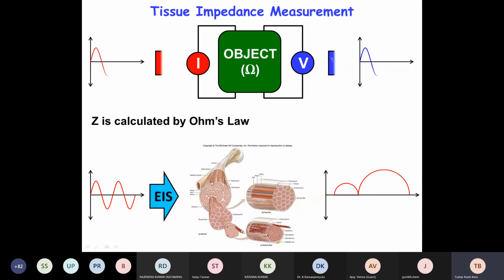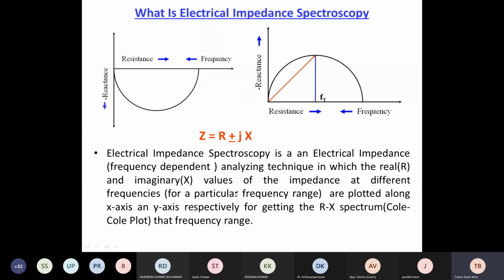After that, the impedance spectra is developed, and that spectra is analyzed for getting the equivalent circuit of the photovoltaic cell. After getting the equivalent circuit, we will be able to detect whether any junction capacitance or any resistance created by the junction, that type of properties, are obtained as per our design or not. So that type of material testing can be done by EIS.